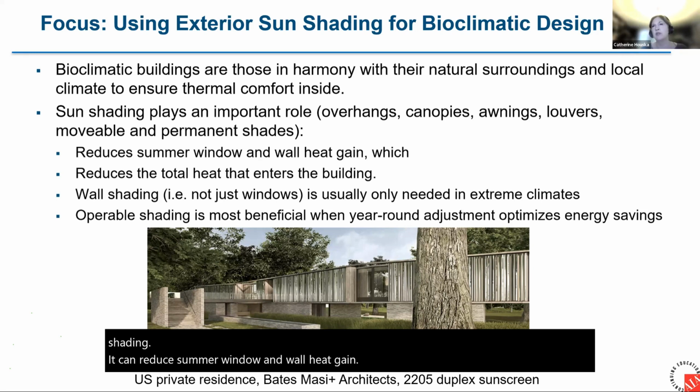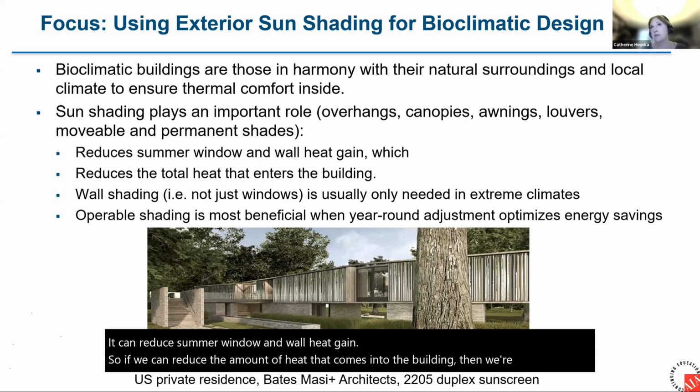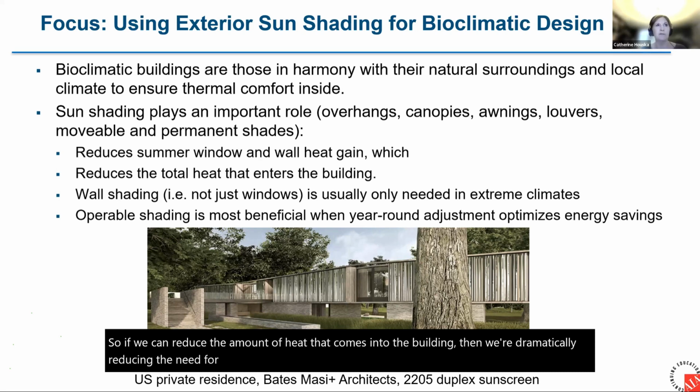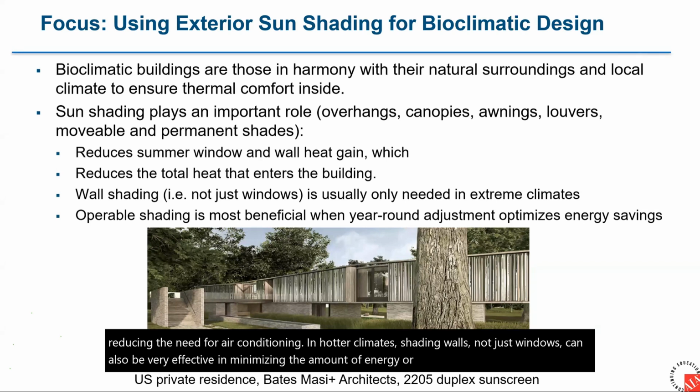So if we can reduce the amount of heat that comes into the building, then we're dramatically reducing the need for air conditioning. In hotter climates, shading walls, not just windows, can also be very effective in minimizing the amount of energy or heat that is transferred into the building.